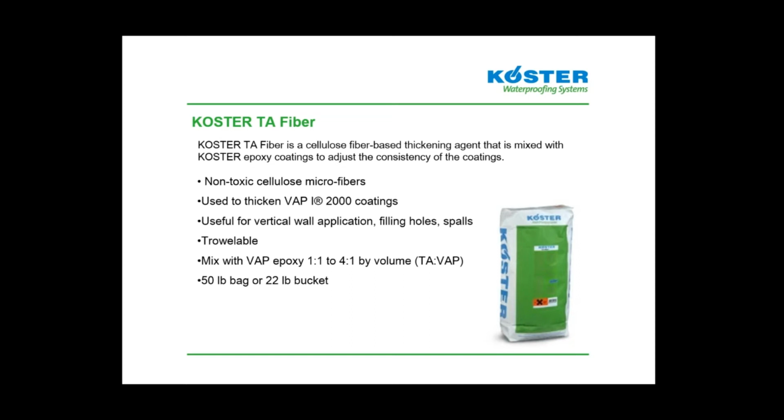This is much less harmful. This is a non-toxic, food-grade cellulose fiber. It's used to thicken coatings for filling holes or spalls. Primarily, we're going to discuss later how we seal cracks and saw cuts and other kinds of non-moving joints.